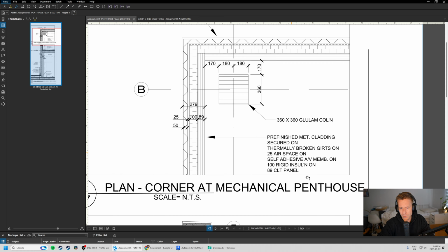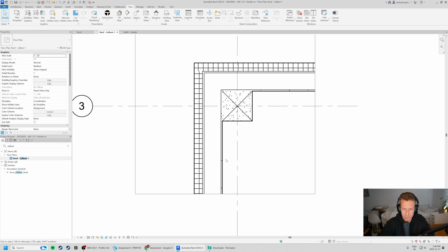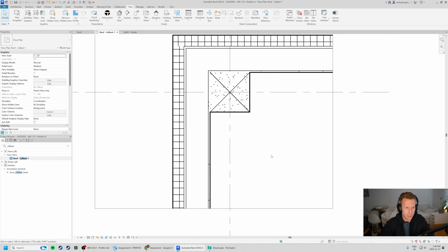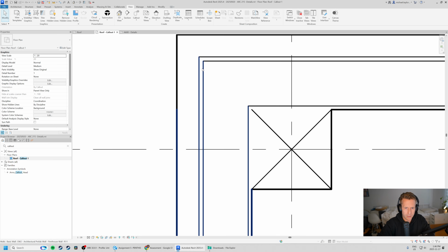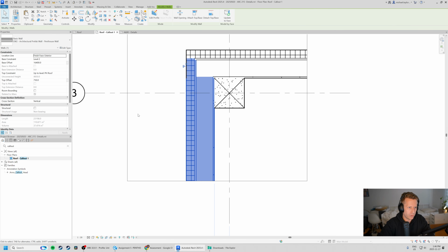So in fact, in the mechanical room, I'm probably going to use studs up here. We probably don't need that full CLT panel, just because it's exposed to the inside. And I think we're allowed to do it, but mechanical suites might make more sense to have just some simple drywall. So I'm just going to double check in here. I did this super quick, so I can see I've got some sort of airspace in here, but let's give ourselves some more thoughtful ideas here.